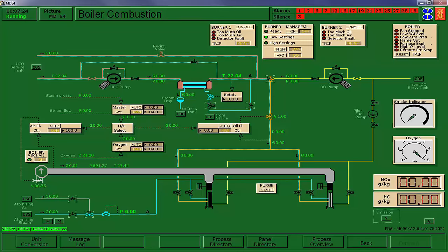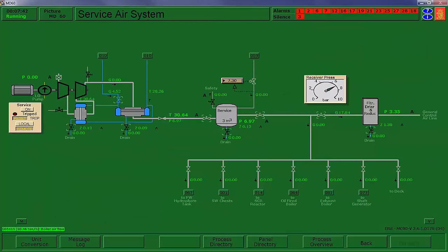These are your dampers. You have a top-fired boiler with two burners. That black box represents a closed register. We'll go ahead and hit start. You'll see those open. You'll see the flow rate come out. We're purging. Now, we're going to need atomizing air, which is coming down here off the ship service air system.